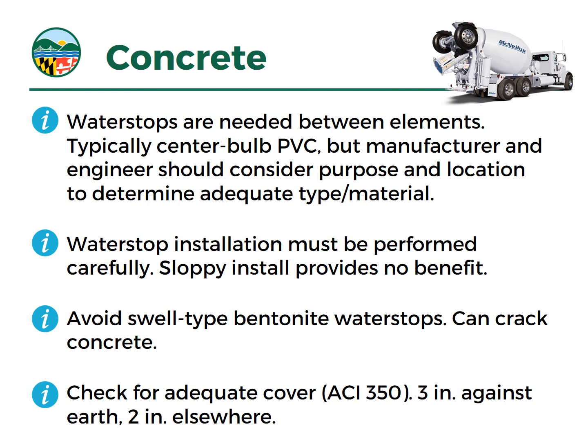We do recommend water stops. We would recommend the center bulb or dumbbell type PVC water stops, but the manufacturer and the engineer should work together to determine the purpose of that water stop and the location, to size the right one and get the right design. These water stops are really your best line of defense between separate pours, and that bulb can be designed in all sorts of ways to allow for joint movement or whatever is needed.